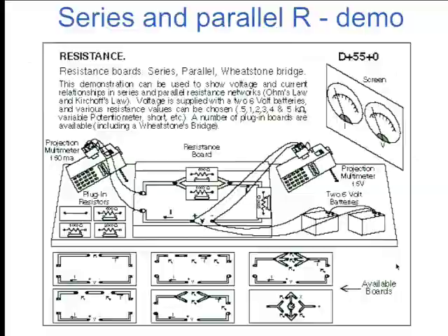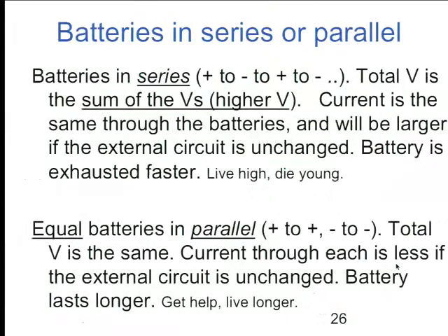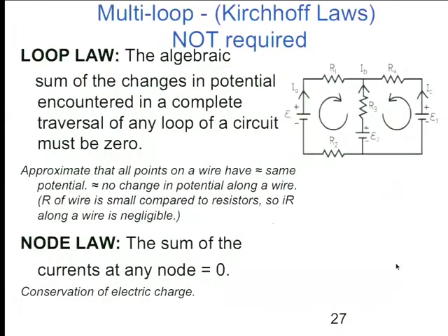And well, here's about meters, and here's that thing. Okay, now batteries in series and parallel. Or here's the Kirchhoff law thing, and that is that the sum of the voltages around the loop has to add up to 0. Because you start out someplace, you end up with the same. This raises the potential, this lowers the potential by the same amount. This is like water pumped up and flows down and loses all its energy. So that's the law. And the other law of Kirchhoff is that as much current flows into a circuit element as flows out.